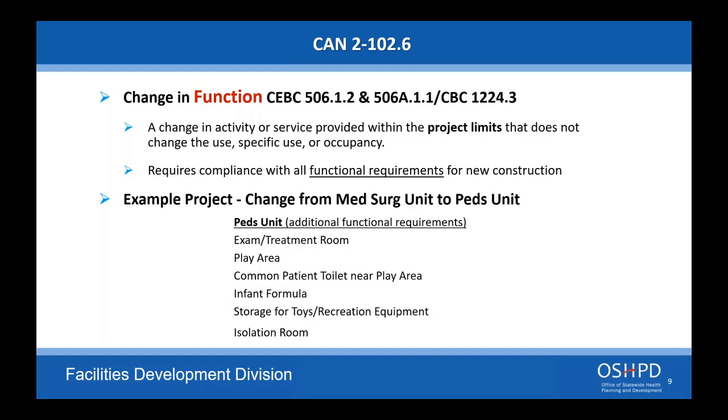Great. Here's a next question for you, Richard. If you need to replace the windows on an existing hospital that are leaking, do we need to comply with Title 24? My concern is that the window-to-wall ratio will be non-compliant as patient rooms need large windows on all sides of the building. The answer is no. If you're doing a remodel, the energy requirements do not apply to healthcare facilities for alterations. I thought you were going to go with accessibility there, but I think it's 141 in the energy code. It exempts all licensed healthcare facilities for alterations currently.